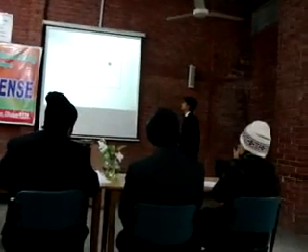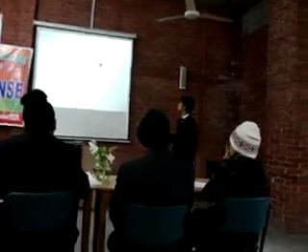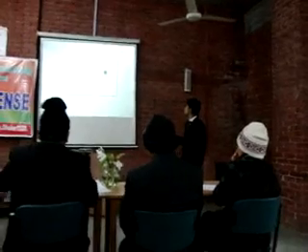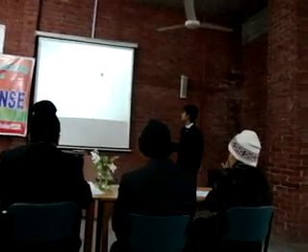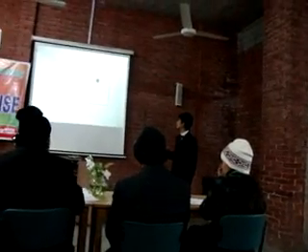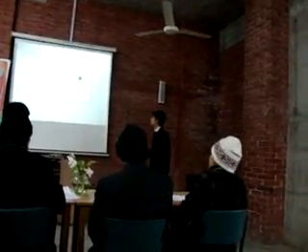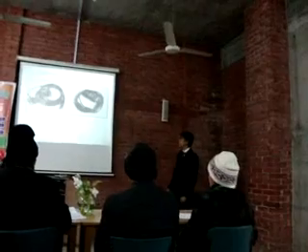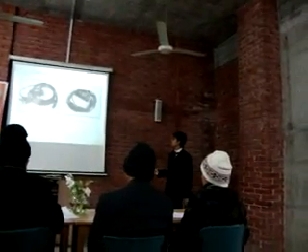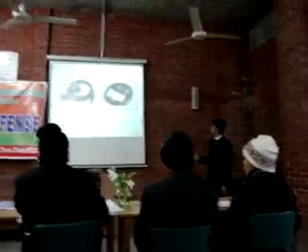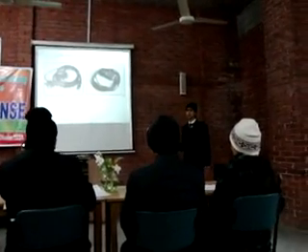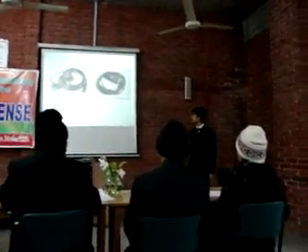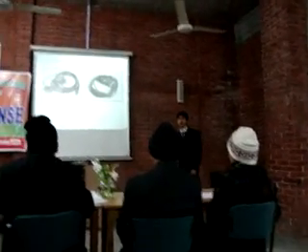And this is the PLC connectivity. These two types of PLC, TSX 57 or TSX 36, are connected to the PC by a serial link connector, and here is the connecting cable, the TSX PCX 1030 cable. These cables are generally used for PC to PLC connection, RS232 cable and USB cable. When we download the program from the PC to the PLC, we need these cables to transmit the program into the PLC.